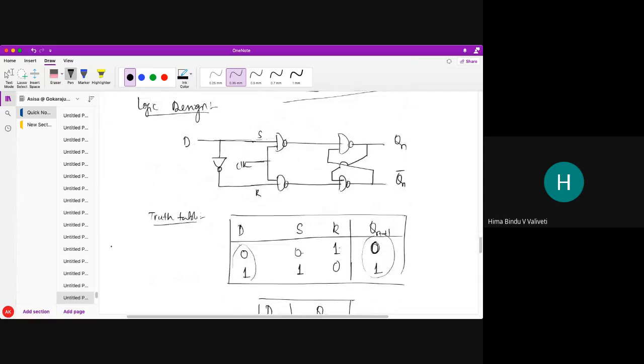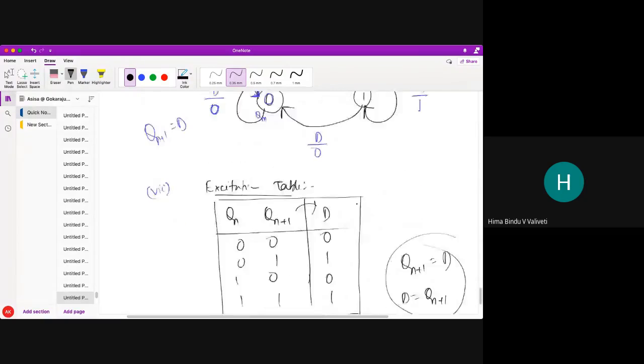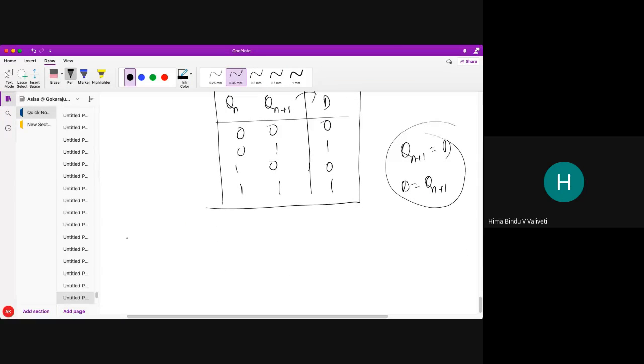So what I have done, I have just modified the circuit like this to get access this way. Where I need some delay in the circuit, I can introduce a D flip-flop and give certain clock pulses of delay. Okay, so this is the basic requirement of the delay flip-flop, and it will be very useful. We are going to use it many times in counters, shift registers and all. I'll tell you in the fourth chapter.